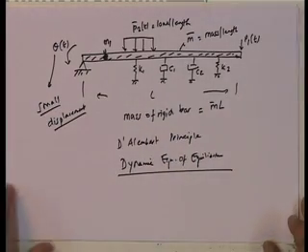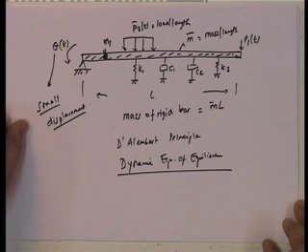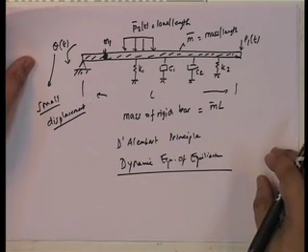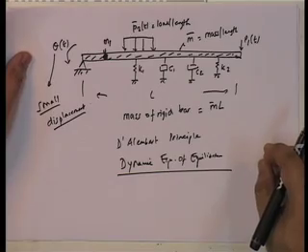Okay. So, now what do I do? Well, to begin with, in the D'Alembert principle, what does it say? Deform the body, displace the body in a shape equal to theta. And the dynamic equation of equilibrium is at any instant of time, take theta, so then theta becomes a specific value, theta at time t. Take the displacement pattern and see what are the forces that are acting on the body. And then take an equilibrium, write down an equation of equilibrium. So, these are the steps that we are going to follow.